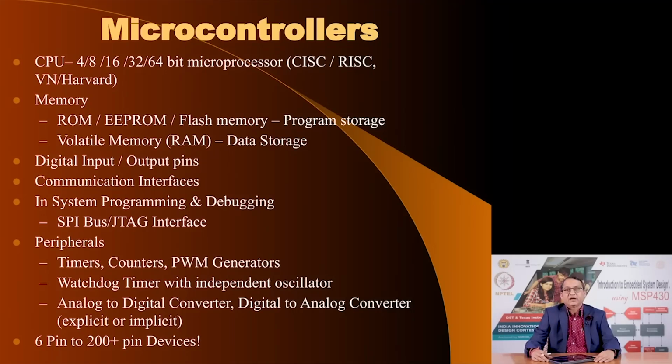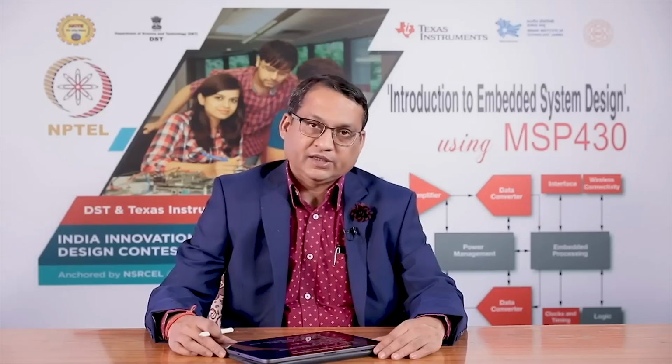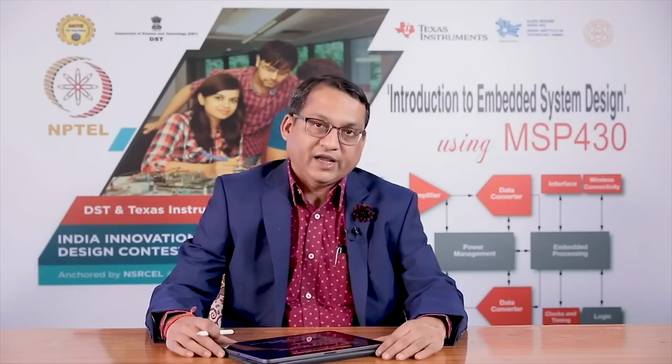The instruction set architecture of such microcontrollers could be of RISC or could be of CISC types. Now, we have observed over time that there are no very strict boundaries between RISC and CISC. Good ideas from one architecture are often borrowed and implemented in another architecture. We will see traditional RISC or manufacturer defined architecture. If the manufacturer says theirs is a RISC architecture, you might find certain features which actually belong to the CISC category and vice versa. But yes, these are two dominant architectures that are available.